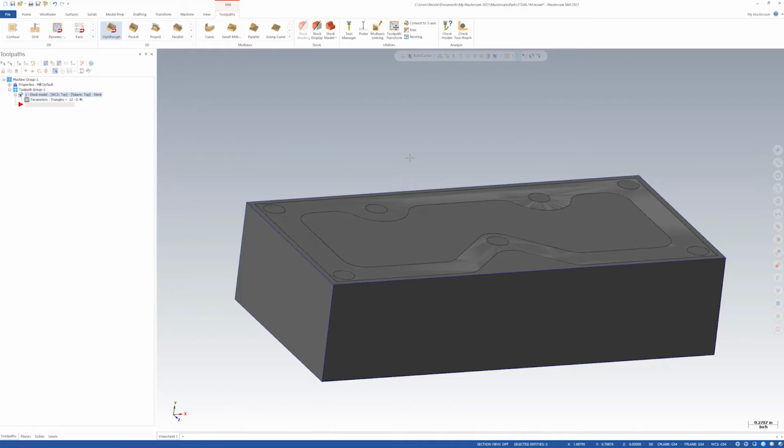Alright, so the first toolpath we're going to be using is a facing toolpath. This is important to establish that top face before we start all of our other toolpaths. This way, as we're finishing pockets or holes or threads, we can measure the depth based off of that top surface right on the machine and make corrections as needed, and we know it's accurate because we've already created that top plane, that top surface.